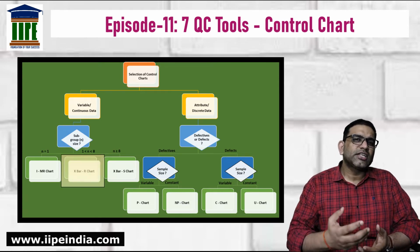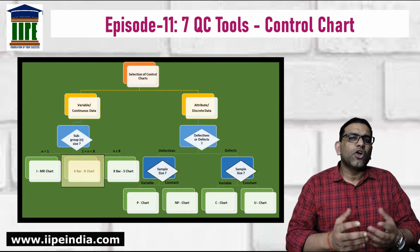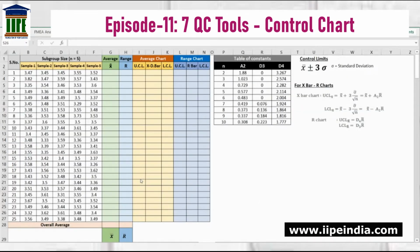Let us try to understand the most commonly used control chart, that is the average range chart, also called the X bar and R chart. So, as you can see on your screen, we have collected the data for a subgroup size of 5 and for a subgroup frequency of 25. Now we are going to create an X bar R chart for this selected data.